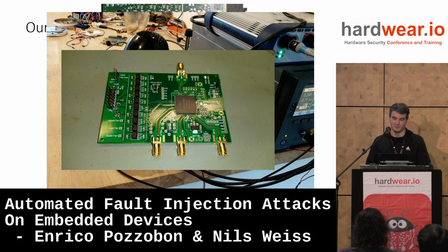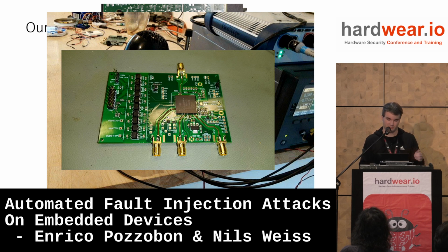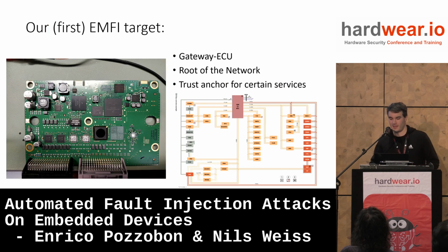And we ended up even having to build our own PCB so that we could perform side channel attacks and fault injection on this. So it was quite a lot of work, very hard to automate. So we decided to later switch to EMFI, or electromagnetic fault injection, which has some advantages. For example, we don't need to modify the board at all. We can just go there with our electromagnetic fault injection device.